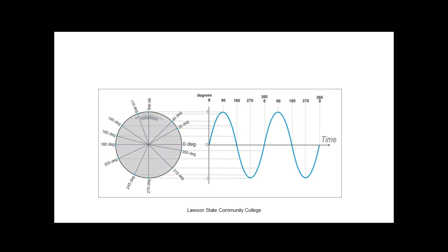And when you look at the actual wheel that it's spinning around, here's 45 degrees right here. And look where it's at. Is that half? No, that's about 70.7%. Exactly. Where does half occur? It occurs right here, which is what? 30 degrees. So at 30 degrees, it's one half up. Not 45 because it's nonlinear. It starts off going almost straight up, and then as it goes up, notice it varies as it goes up. So 30 degrees is when we get to half volts.